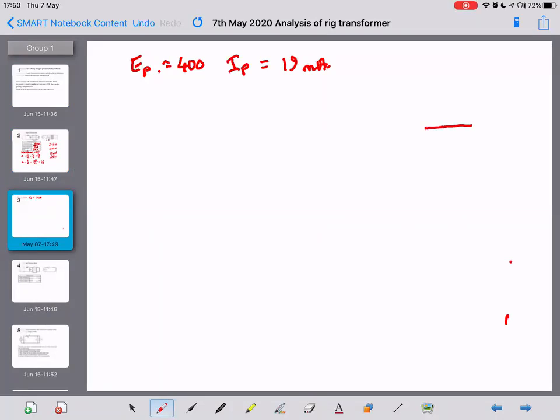Remember our triangle. There's P. We know that. We measured it. It's 2.6 watts. But a power triangle also includes Q and S. And it includes a phase angle as well.